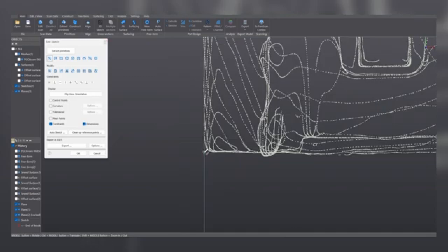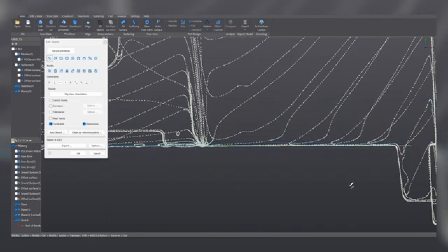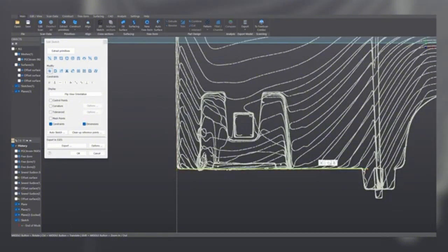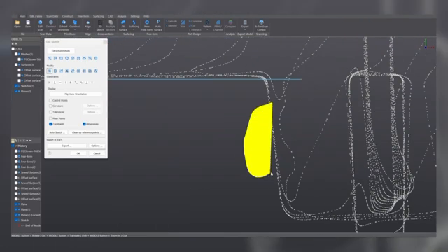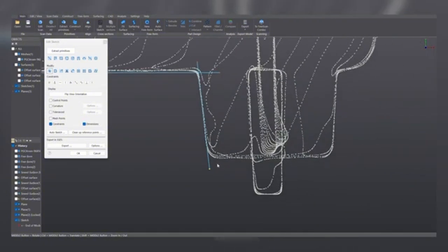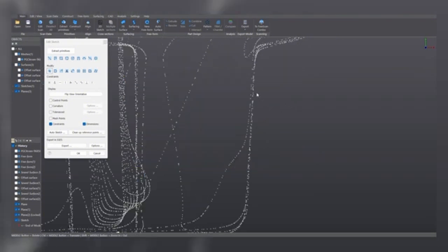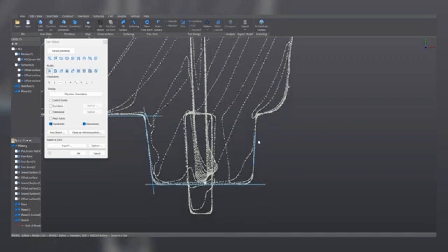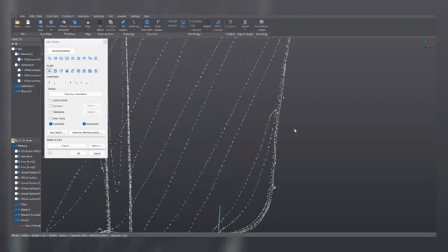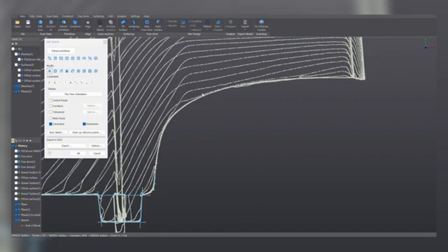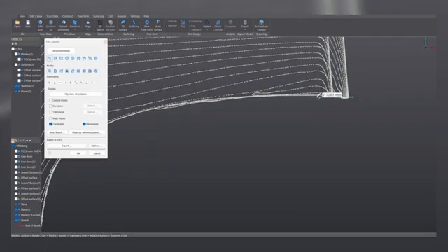Now, what we do is let's start here in the origin. Let's draw a horizontal line like this. Actually, let's click on it and make sure that it's horizontal. And now let's reproduce this geometry. How? Well, with the Shift key and selecting the points, you can quickly best fit lines. Here, actually, I will eyeball one horizontal line on the top of this shape. Here, let's also best fit a line, like so. Let's extend it a little bit more. And to close it here, let's extend this line. We are going to trim it afterwards. And here we can do the same. Let's best fit a line here. That looks good. And for this shape, let's do it later. Let's finish the process with a horizontal line over here.